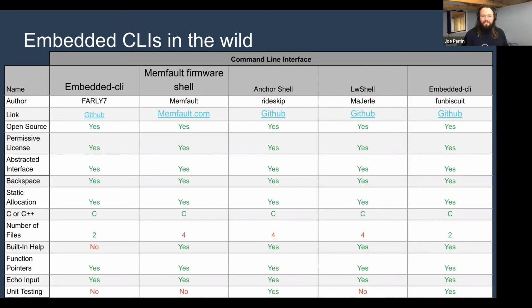Yeah. At a previous job, I was very focused on security. I hope it comes to mind at all the right times. But don't expose things that you don't want the general public to be able to access later. Put in features for that right at the beginning: passwords or build flags, whatever's needed. The FDA is really looking at this too. I don't know if anyone online is doing some medical related stuff, but they will catch you even if you use the same password on every device. That's a no-no. You've got to have device independent passwords.